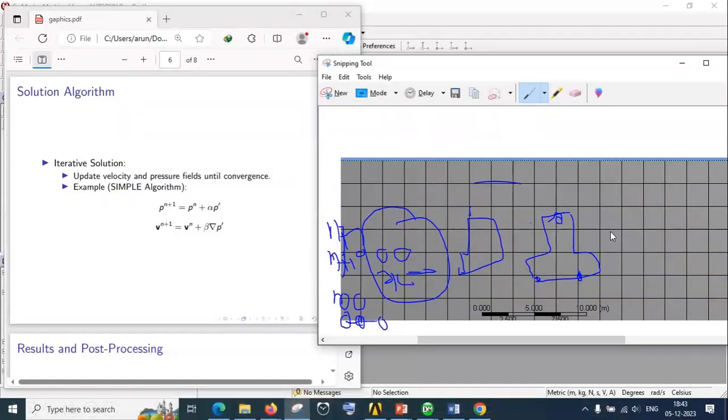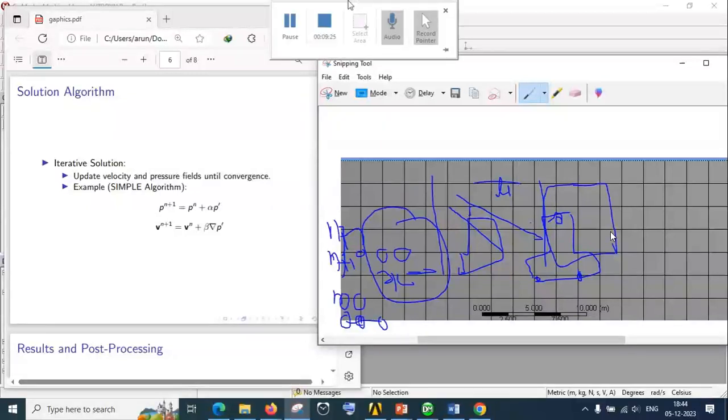To solve this we make a banded matrix to solve the linear system of equations with the TDMA method, analyzing the effect on velocity and pressure at each and every node.